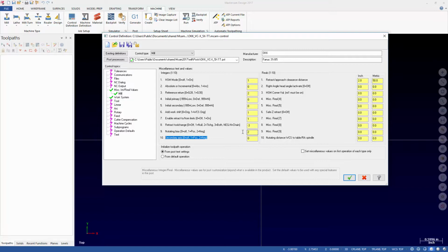Jeremy says he kind of handles that with forced tool change in the toolpath. That's certainly an option. That does change the NCI G code from 1000 to 1002 to make it go through the actual tool change. And that way every path starts and ends with an actual tool change. And that's certainly a valid way to do it.